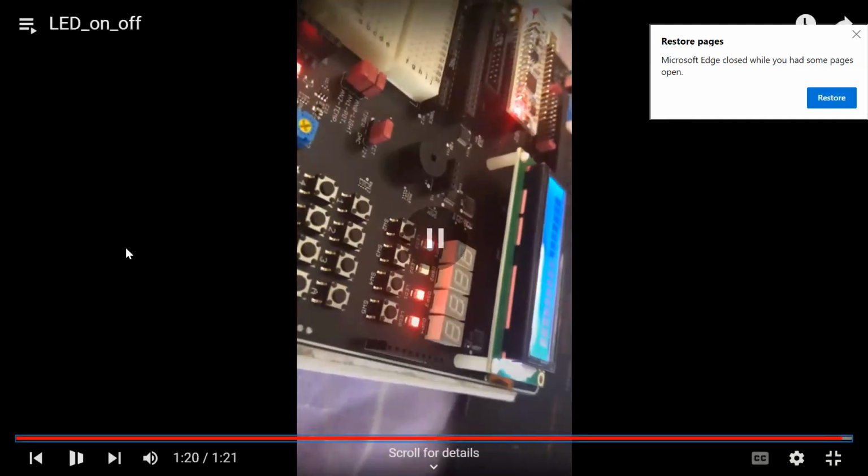Yeah, this is a very important thing. As you see here, guys, you can see all of them are on at the same time, which is not true. What I do, I turn one on, the other ones are off. One on, the other ones are off. But because I do it very fast, you will see it like all of them are stable. And this is very, very important, because I'm going to use the same idea later.